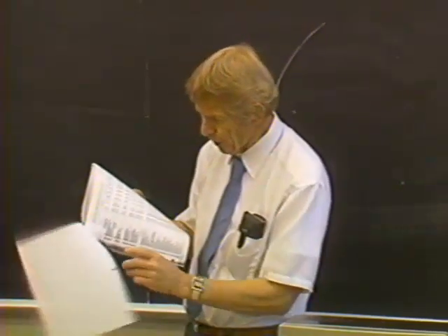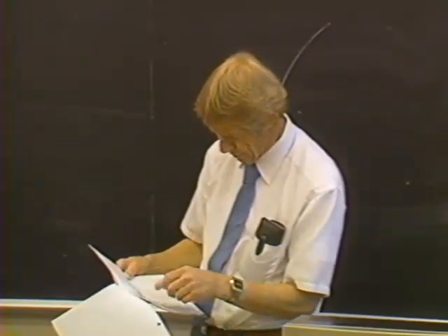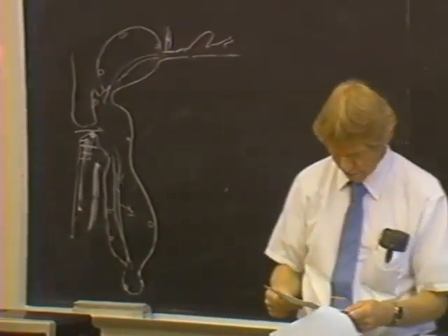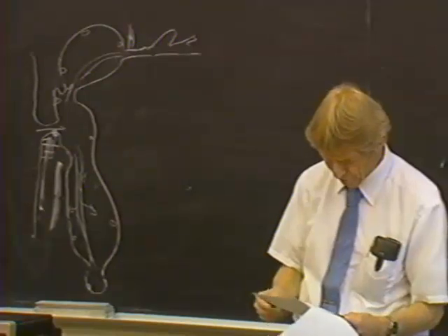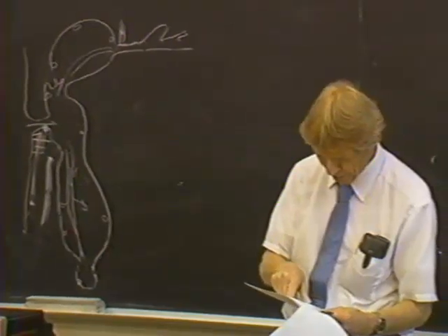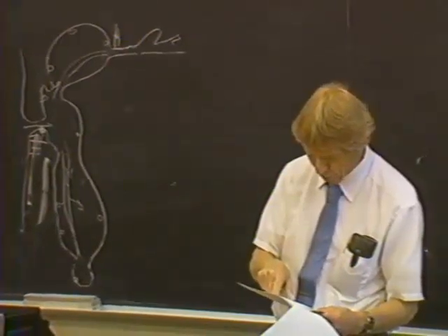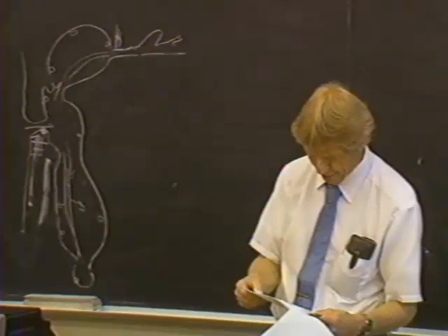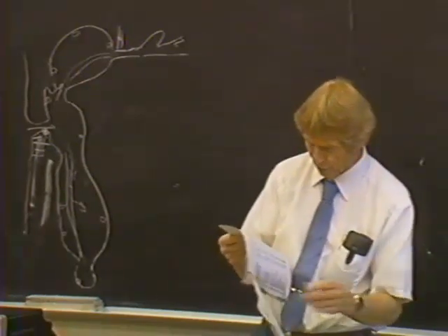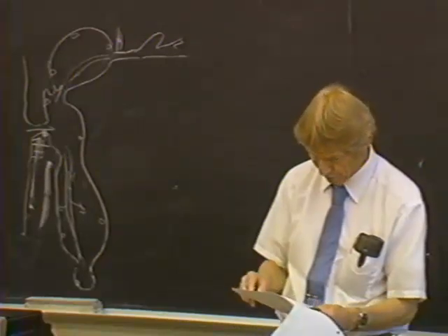Then on following pages, they have tables that give the position of the other temporary station, then the differences in highs and lows elevations, the first two are time in hours and minutes, and then differences in high water and low water elevations, so that you can take the tide at the Golden Gate and then apply these factors to get the high and low water tides at other locations in the bay system.